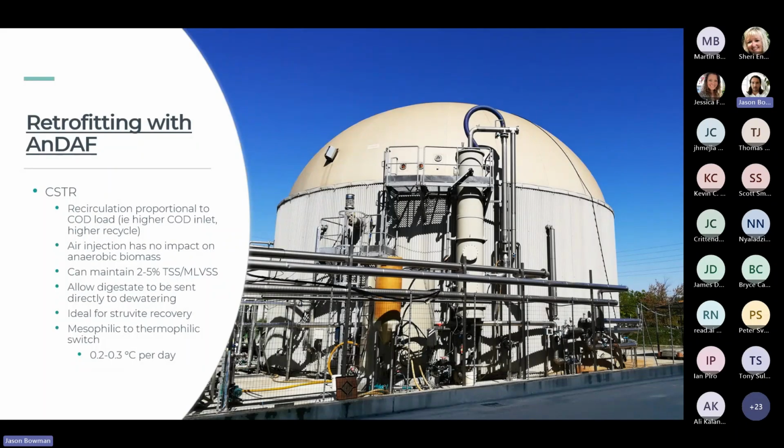Number two, some of you are probably already thinking, well, wait a minute, you're using a DAF process and DAFs have air. You're using this to recirculate. Doesn't the air impact the operation? The short answer is no. The level of solids that you typically deal with in digestates and the level of thickening is much higher than, let's say, your normal DAF operation that you might find in a pre or post biological treatment or aerobic treatment system. The other thing to think about is the saturation values are also carefully controlled in these systems, so we're not just injecting air at a crazy high rate.